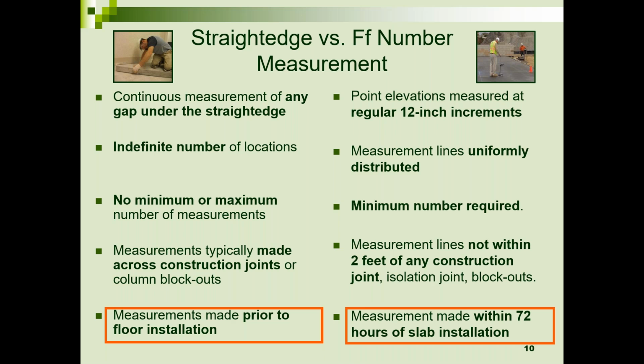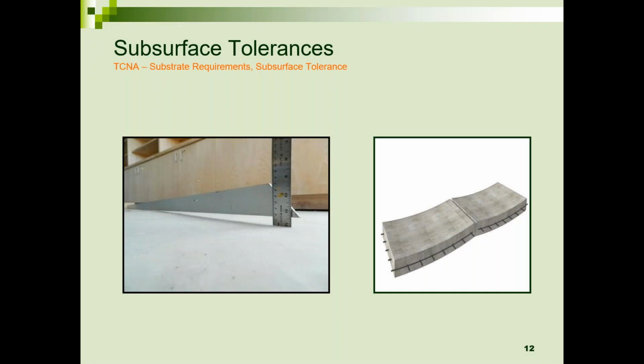And what's wrong with that? Well, I'll tell you. If you look on the right picture there, you've got a deformed, curled slab. As ready mix concrete dries, it will deform and curl because the bottom stays damp while the surface dries out quicker, so you get that upward curl. However, all that deformation is not seen 3 days after the concrete is placed, when FF numbers are measured. So if you're installing tile weeks or months after the concrete's been placed, it now looks like a potato chip, curved, because again, moisture has left the slab, and that deformation is a given.